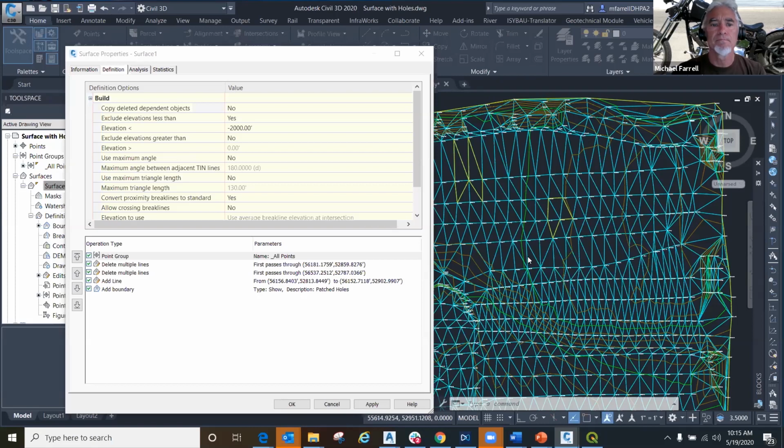No? Anyway, what this guy does, and I use it quite often, especially if I've added contour data and/or optional break lines to a surface that don't come from survey figures. I don't want to keep those objects in my file.